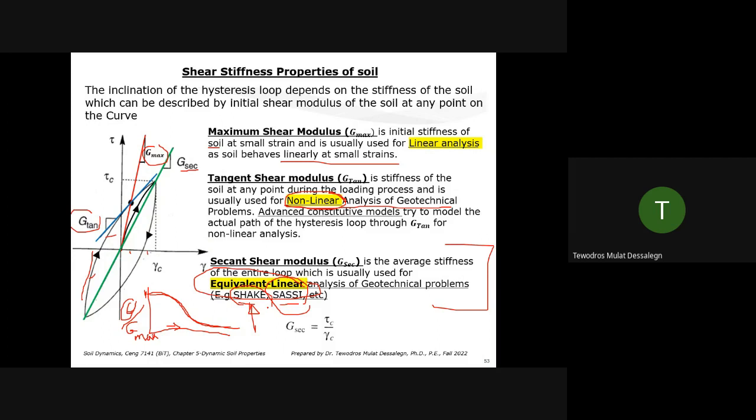Because structural engineers, what they do is they approximate the soil. They either assume a fixed condition or they apply some springs when they model it. And geotechnical engineers assume some approximation on the structure because we are more interested in the geotechnical portion. We do a detailed modeling for the geotechnical part, but for the structure, we approximate just some mass. But when you come to software like SASSI, it models everything as is. And it's much faster than any available software.